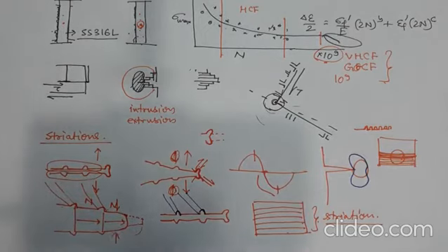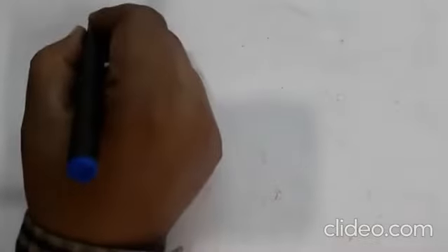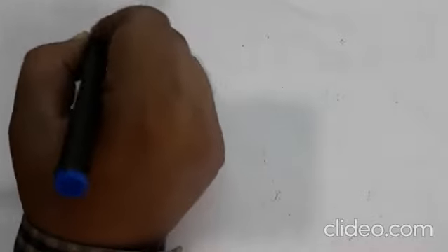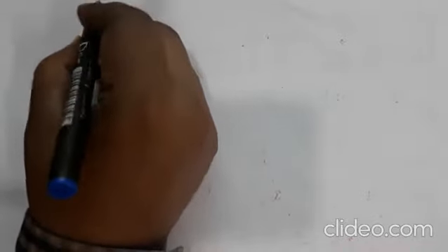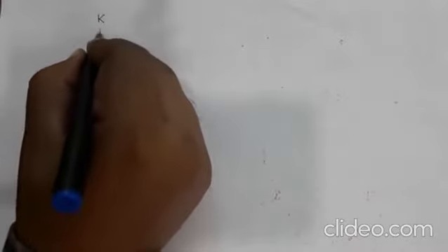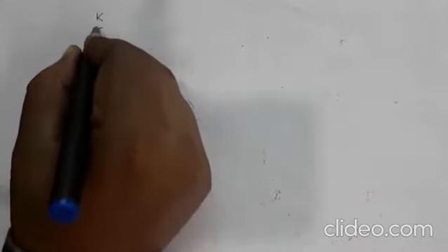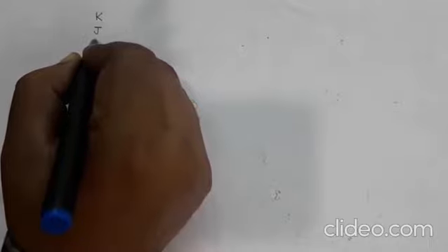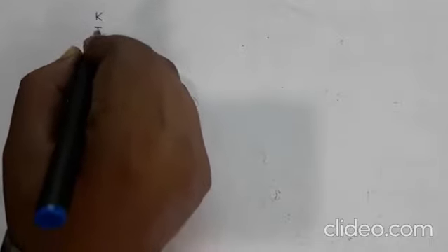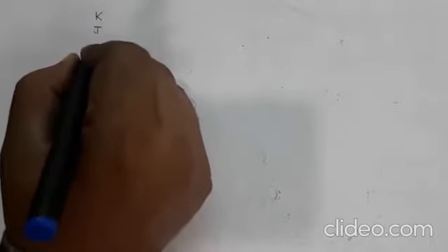According to the theory of fracture toughness, all that we have studied on the crack tip stress definition, the stress intensity factor parameter K and the J integral parameter, need the crack tip to be very sharp.